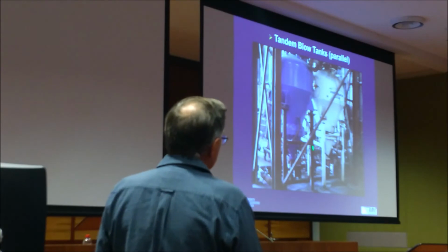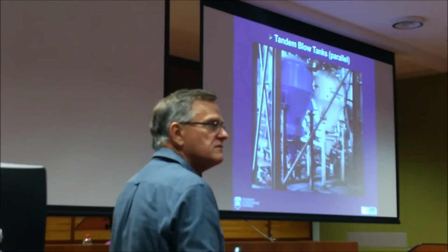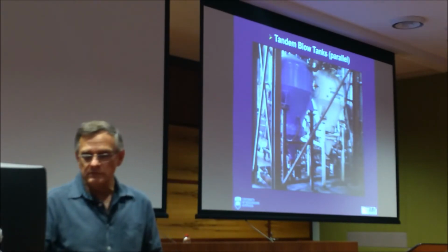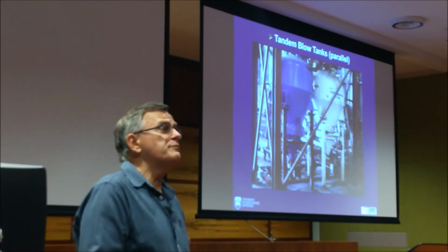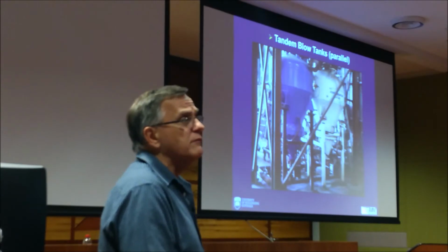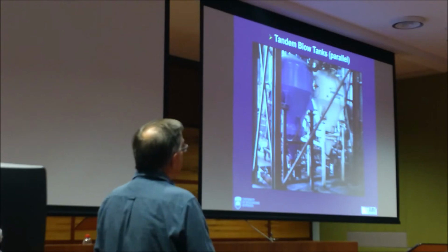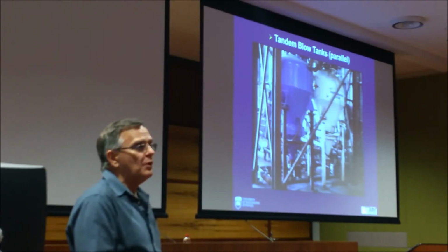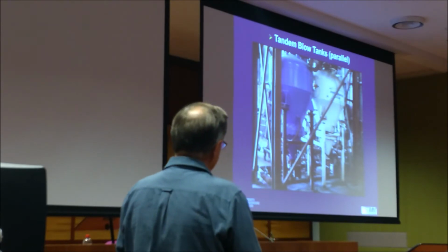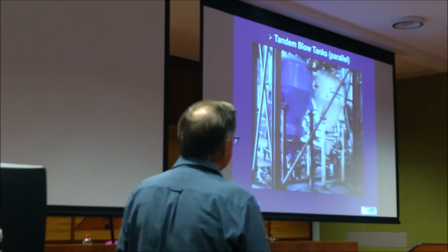So when this blow tank runs out, we just swap over. And you lose a few seconds. So you don't get quite a continuous feed and hence continuous conveying. You might get about 90-95% continuous, but it's pretty close. You keep your pipeline pretty full of material. So this is what we call blow tanks in parallel or tandem operation. Tandem blow tanks. And you'll notice fluidising discharge cone on the two tanks that we have in Wollongong.